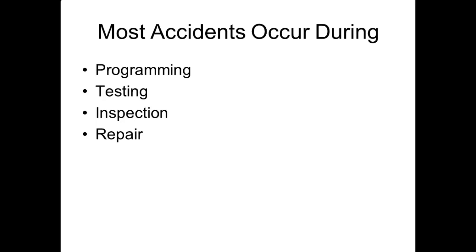But you still have the teach pendant in your hand. You still have the dead man switch in your hand. And you still have to press buttons on the teach pendant to run the program. Robots that don't support a high-speed teach are limited to 250 millimeters per second maximum. That's still fast. So if you have a high-speed teach and you're in that work cell running a program to test it out, you've got to be really, really careful about what you're doing.